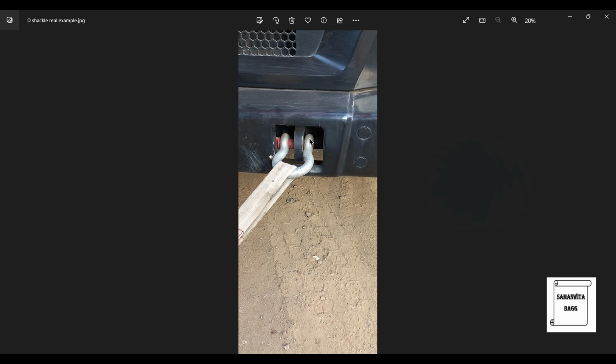Now, this kind of an anchor shackle will be subjected to a maximum temperature of 204 degrees Celsius. This is as per theory, and the negative temperature is minus 40 degrees Celsius. So we will see how to find out the thermal analysis of this shackle. Also, you need to note here that these shackles will be subjected to a convection of air only. There is no other type of convection possible.